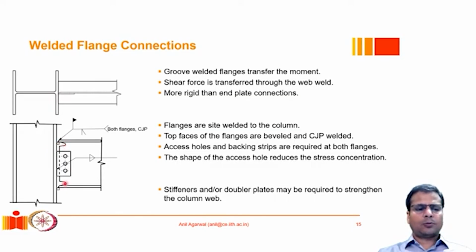These access holes also play a very important role in separating the moments from shear. Because of the presence of this particular geometry of the access hole, and if you go to the detailing guidelines, you will see that this geometry is very specific and one needs to satisfy that specific geometrical requirement in order to avoid any stress concentrations in this region. Because of the presence of this access hole, any shear force demand does not get transferred to the flange, because if you can imagine, if we move this beam up or down, the flange can very easily deform and would not transfer a lot of shear force to the weld, and most of the shear force will get transferred through these bolted joints.